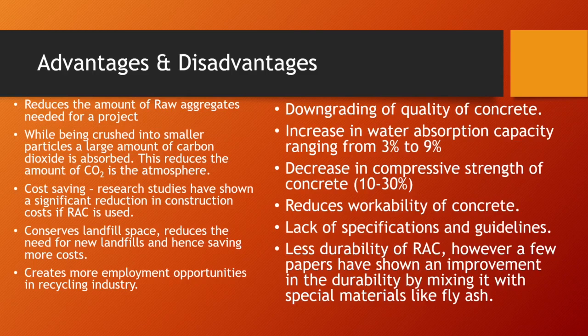And the disadvantages: it's a downgrading of the quality of concrete. If you've got a concrete slab that's intact, that's far stronger than when you break it all up into little bits. There's an increase in water absorption capacity ranging from 3 to 9%, because you broke it up and created more porous surfaces, so there's increased potential for absorption. There's a decrease in compressive strength of concrete of 10 to 30%. As I've just said, when you break it all up from a big slab, it's obviously far weaker in its constituent, smaller parts. It also reduces workability of concrete.